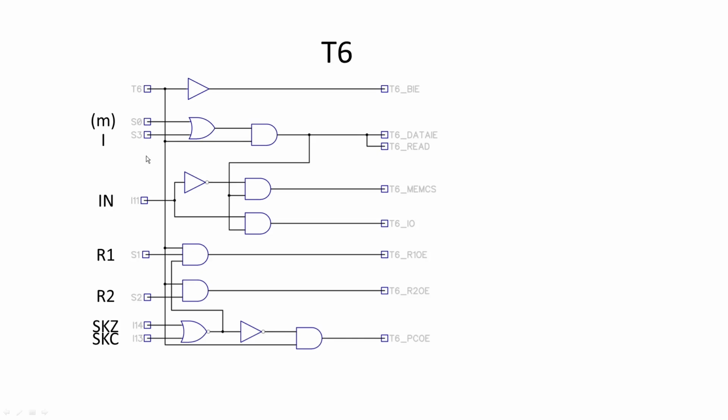So you can read, well, immediate mode will only ever be for memory really, because that's the next byte of memory. But we don't need any more decoding logic. We're just getting the data for the B register from R1. If we're in addressing mode 1, which is R1, and we've got T6 on, then we'll do an R1 output that goes into the B register. Oh no, we'll come to this bit in a minute. And R2 is the same, so we can put R2 straight into the B register. So R2 output goes into the B input.